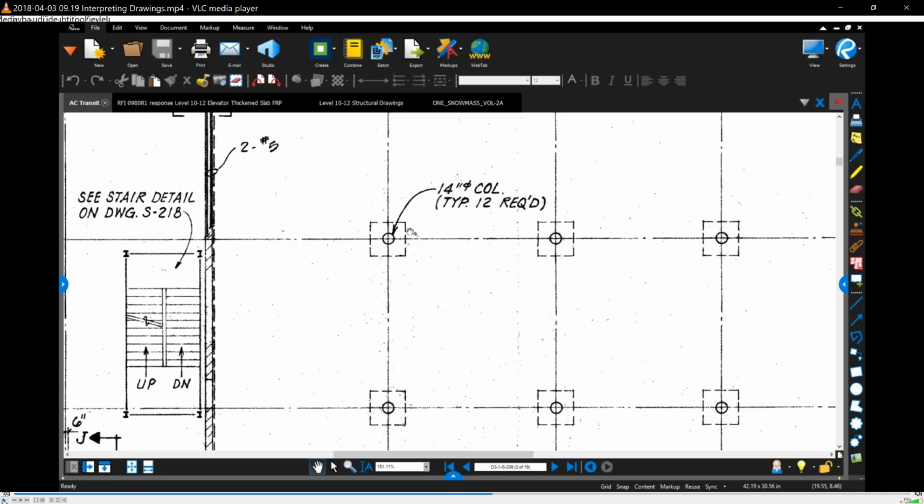And the plywood comes in 4 by 8 foot sheets. So once you put all the formwork on it, it ends up being 45 inches by 45 inches in plan and 7 1/4 inch deep. I think in the recording I said this is 8, but it kind of depends. So the edges of the drop cap are dashed because they're below the slab, but the edges of the column are solid, not dashed, because they're above the second slab.